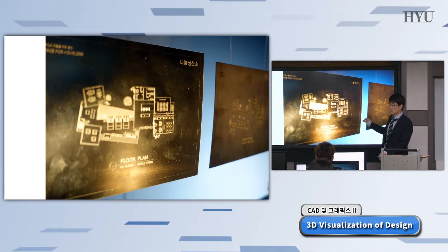Laser cutting usually penetrates metal or wood, even paper panels. But by controlling the power intensity of the laser, we can make scars, scratches, without cutting it out. So given this metal plate and a vector-based 2D image, the machine can generate this kind of scar, an etching-like visualization.